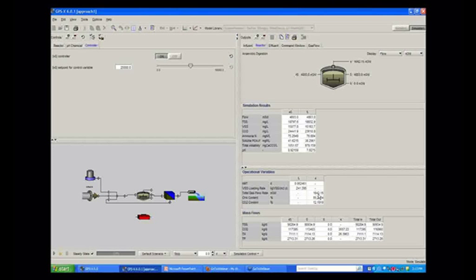So when I run this simulation to achieve a concentration of 25,000 in this reactor, I can see the concentration in the reactor going up to 24,843, and our gas production increases to 1685 from 1640. So there is a slight increase, or almost 2 to 3% increase in the gas production if we increase the concentration in the reactor to 25,000.